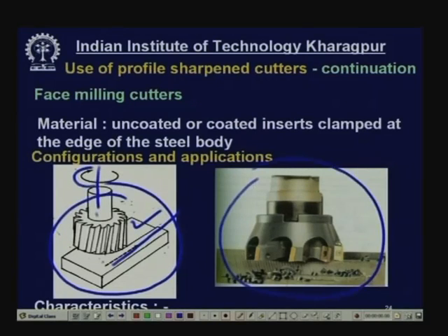This is the cutter, and these are the cutting teeth. These are clamped carbide, and in this case these are all coated. Have you seen? And this is producing this flat surface, and this is the original surface, and this is the flat surface it is producing, and is removing material very quickly. These are the chips.